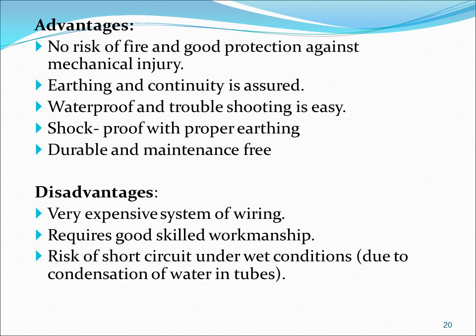No risk of fire and good protection against mechanical injury. Earthing and continuity is assured. Waterproof and troubleshooting is easy. Shockproof with proper earthing, durable and maintenance free. But disadvantages are also there along with the advantages: very expensive system of wiring, requires good skilled workmanship, risk of short circuit under wet conditions due to the condensation of water in tubes. This is about the conduit.